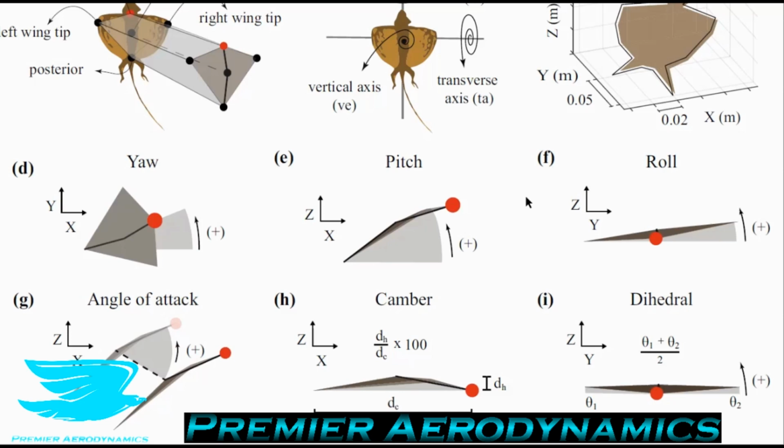The wing that goes higher, the lift that it's producing is now not completely in the vertical direction. There's a part of it which is in the vertical and a part of it which is in the horizontal. That means technically you're not producing as much lift on this surface as the other surface just because of this geometry. Also, the angle of attack that the wing is seeing with the flow is now reducing. So you're getting less lift actually being produced because of that factor as well.